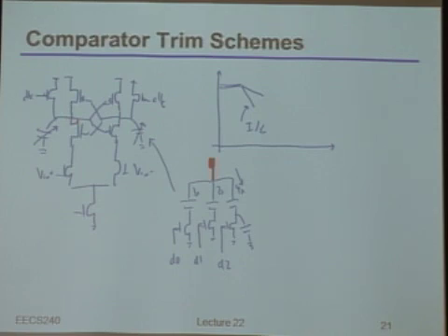Which, if you guys remember, I said that you generally want to make those comparators small, right? Like minimum size. Well, 100 femtofarads is probably way bigger than anything remotely related to what you actually wanted in your comparator. So in other words, the badness here is that you have to take that full dynamic range in the DAC and put it right at the most sensitive node of your comparator. And so if there's any small parasitic that you can't get rid of, it will scale with the resolution of your DAC, and it will directly eat into the power you have to spend to actually get this thing to work. Make sense to everybody?